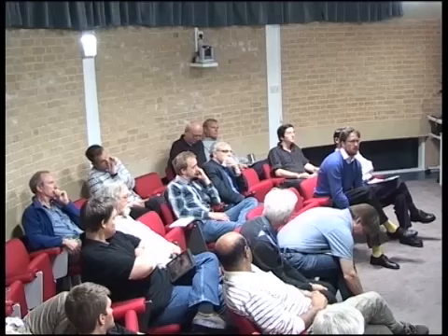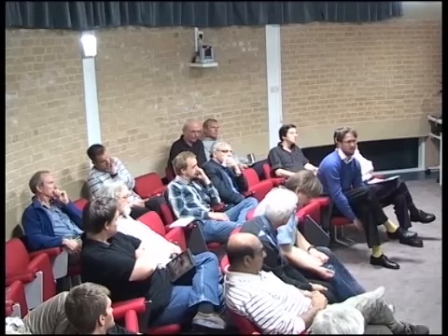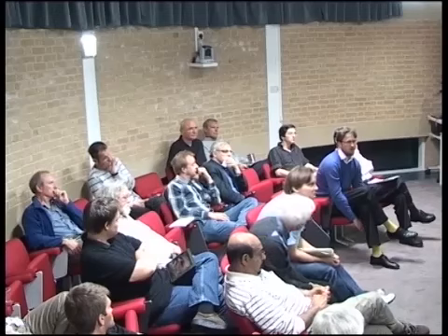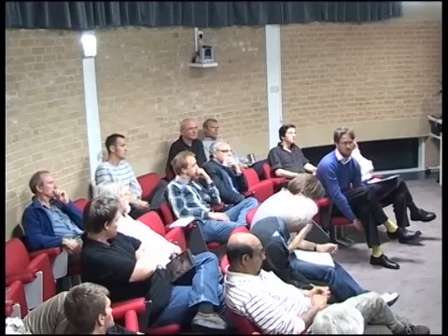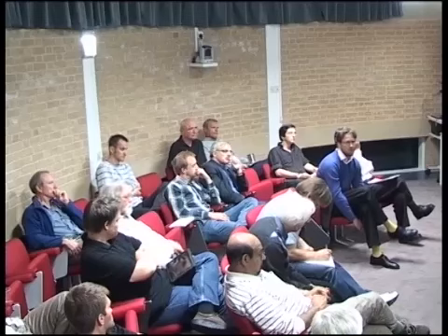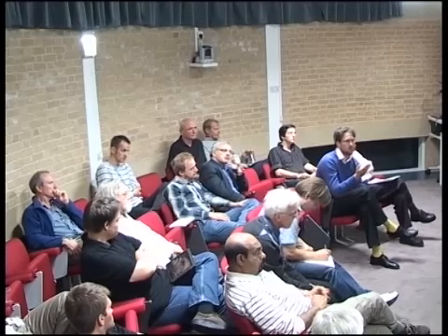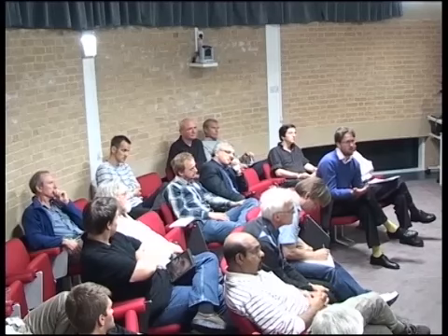The domain decomposition that you do, if you do it based on the physical grid, which is what you're doing, you're not doing it based on the physical process. Well, but no, I'm claiming you're doing it based on a performance model. If you just take the number of grid cells as your performance model, then I agree you have a problem. But you can weight your grid cells. Now the next question is, how do you weight your grid cells?